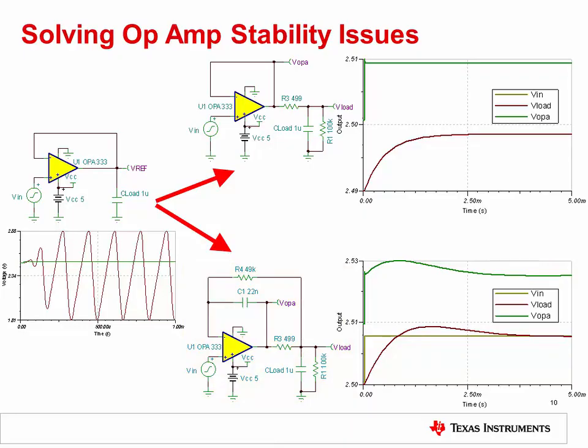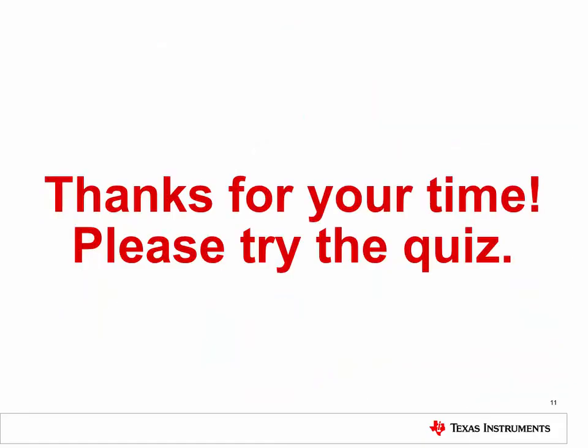We'll explore the different methods to stabilize circuits after we review the necessary theory to understand, simulate, and compensate a feedback network. In summary, this video discussed op-amp stability issues, common circuits that cause stability issues, and how to identify stability issues in the lab. Stay tuned for the next videos, which will cover Bode plots, basic stability theory, simulating op-amp stability in SPICE, and common compensation techniques.